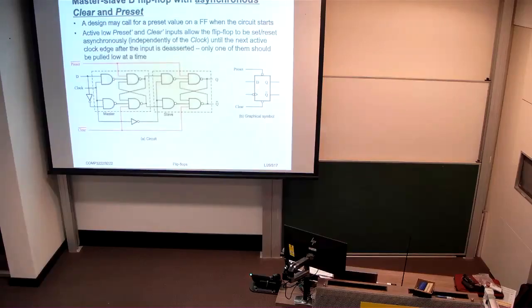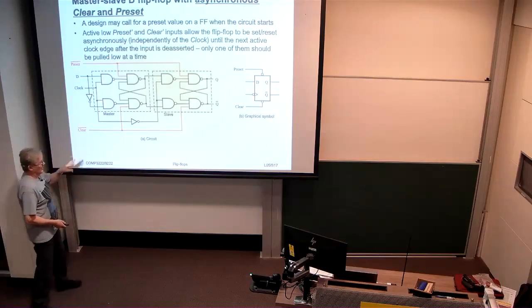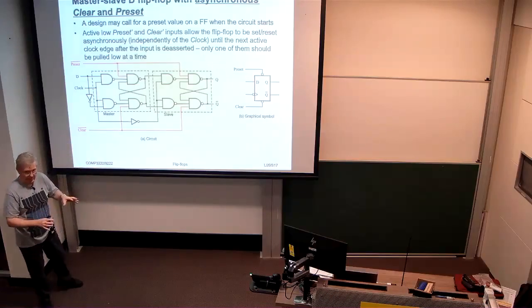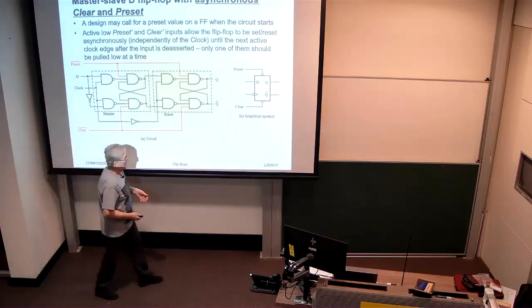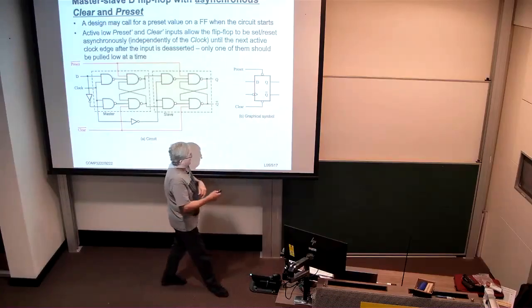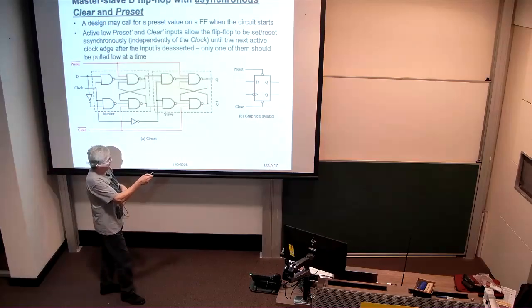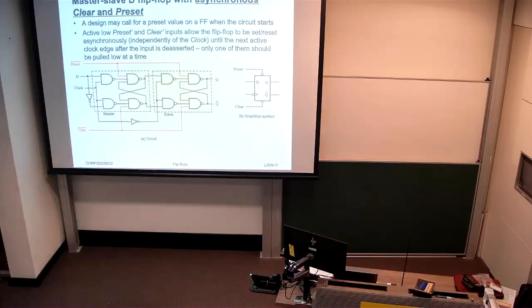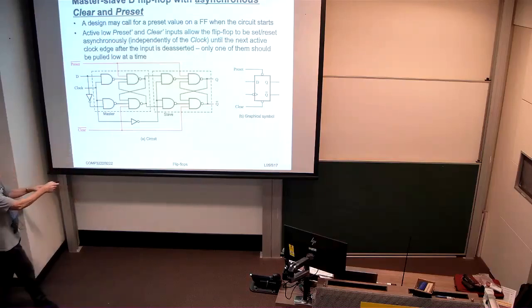So how do we design the circuits to asynchronously clear or preset the flip-flop? So this means to be able to set a value of 1 or to clear the flip-flop to only have a value of 0 when we initiate the circuit. Graphically, the way this is represented within the negative edge triggered D-type flip-flop is to have separate inputs for preset and clear with bubbles on them to indicate that they're active low. So this means that we have to drive that wire to 0, assert a 0 on there for it to work. Internally, that might look like this.